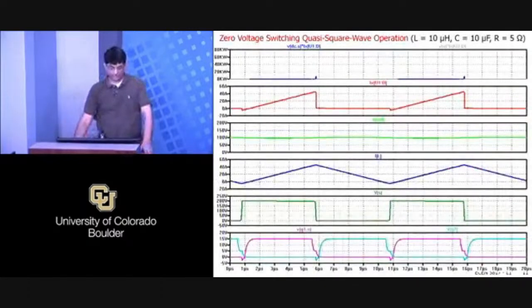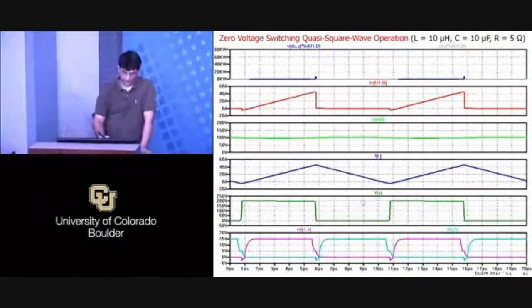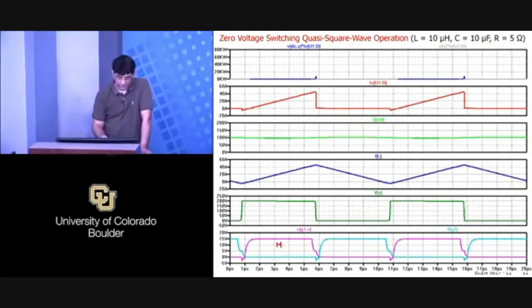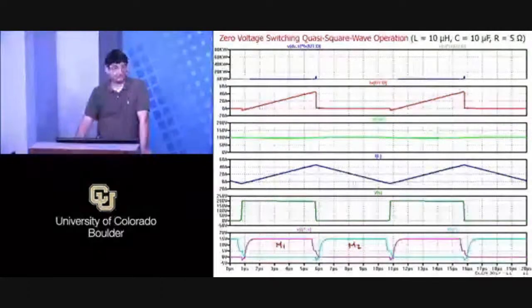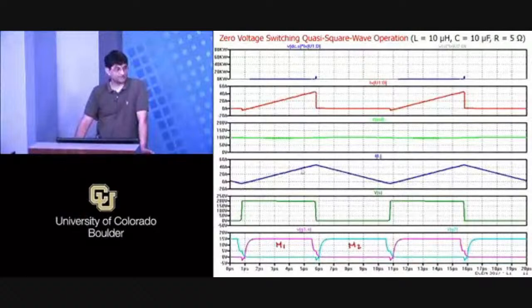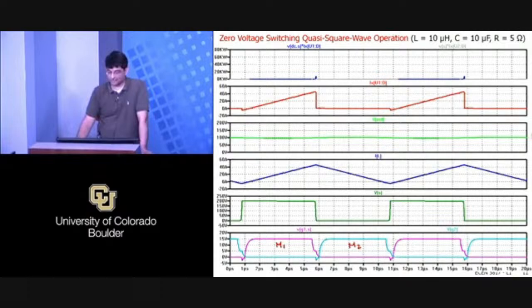All right. Here is the simulation. Again, you have first M1 on here, and then you have M2 on. The switch node voltage looks just the same as before. Here's the difference that we expected, that the inductor current has higher ripple, right? The average value is still 20 amps, but the ripple is considerably higher. In fact, probably 10 times higher, because we have a 10 times smaller inductor. The output voltage has slightly more ripple, but not appreciable. It's still fairly flat.